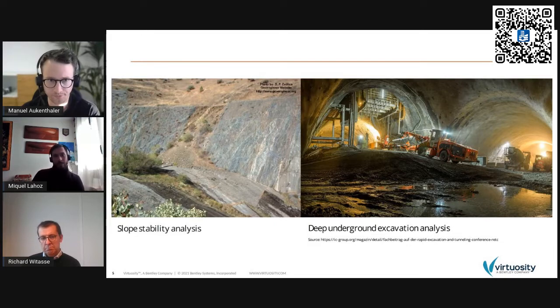Well, the first thing to consider is the in situ stress. In slopes, it's almost fully released because you have a free surface there. And when you're excavating, you are the action that releases that stress. And this in situ stress can be helpful, and it can increase the friction at discontinuities and help lock blocks together.